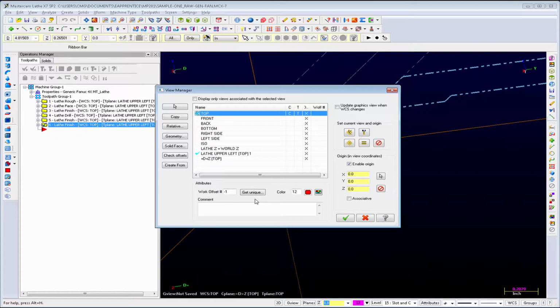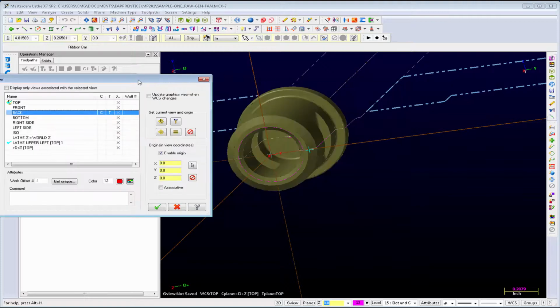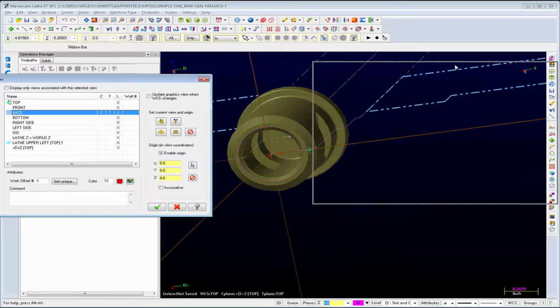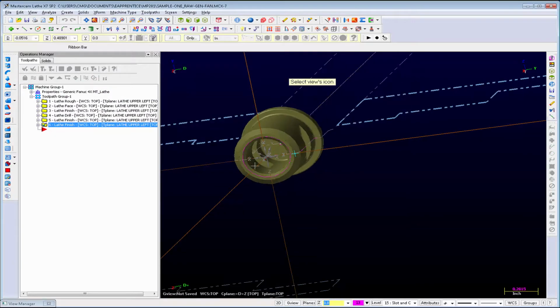For all C-axis tool paths, if you run them from the C-axis menu, those tool paths automatically set the planes for you. Michael's correct that if we want to do any of the mill tool paths on a lathe, we need to set our tool construction plane to back. Back is C0 for our machines. And one of the important things to note when you're looking at the back plane, let me hit select here.